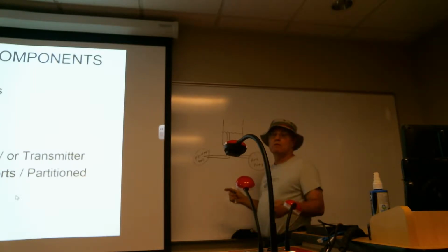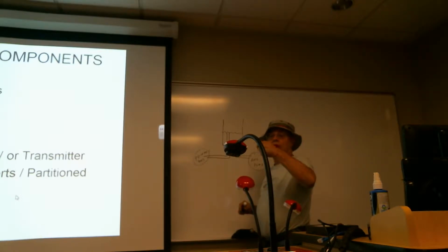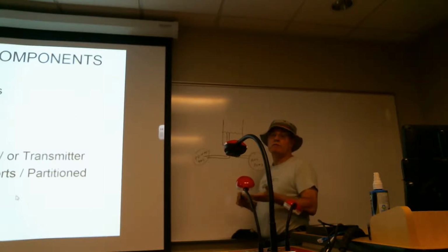So we do this also, like for example, in some motorcycles. If you've got a valve that you can turn on the fuel tank in order to provide for reserve fuel, it does kind of the same thing. What it does is it allows you to drain from the tank from a lower section, so it provides for kind of the same idea.